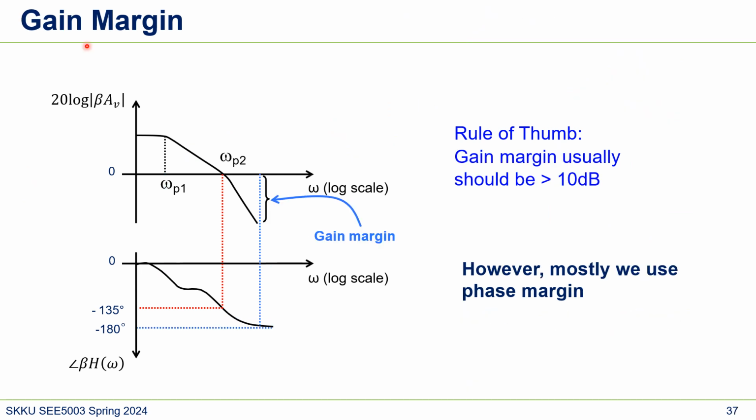Similarly, we also have gain margin. Gain margin means the gain at 180 degrees. The gain at 180 is a lot less than 1, right? As I said, at this point the loop gain is 1. And at this other point, maybe it's less than 1, a lot less than 1. Well, actually, we can calculate it in this exact example because we know that here it is minus 40 dB per decade. We know the slope, so we can calculate the gain here.